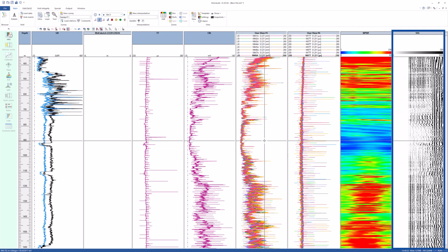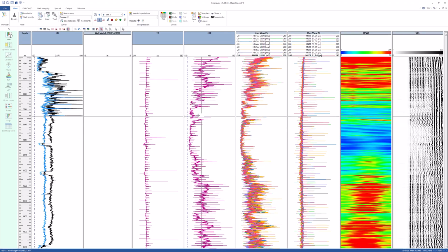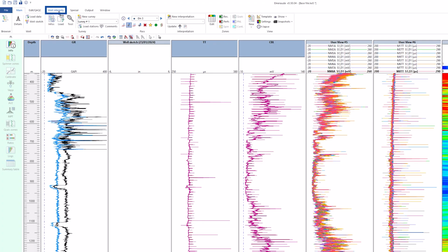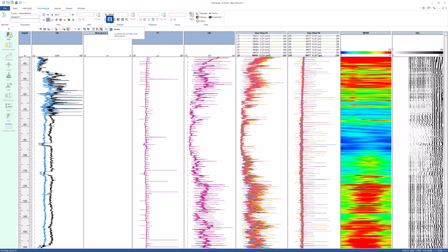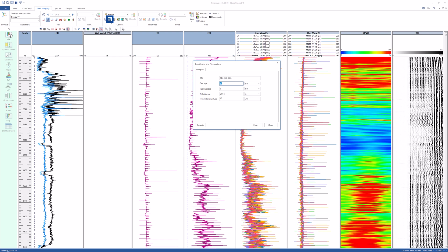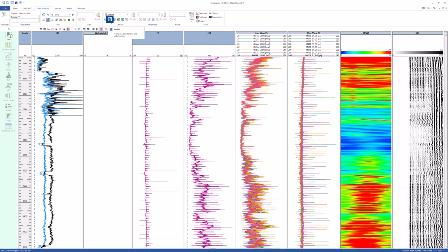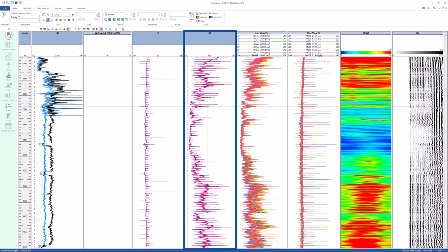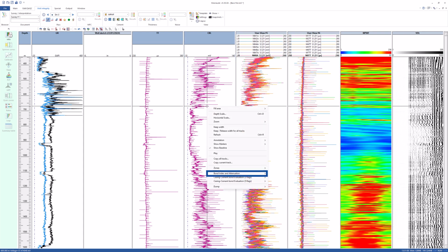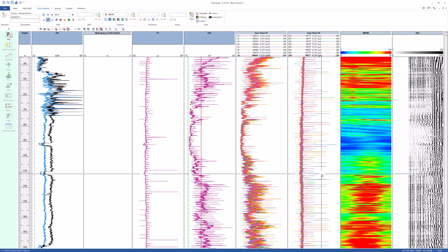The cement evaluation workflow is conducted from the Well Integrity tab. The first icon corresponds to the bond index and attenuation calculations. The selection of the endpoints can be done interactively on the CBL track. Right-clicking on bond index and attenuation on the CBL track shows free pipe and 100% bonded levels.